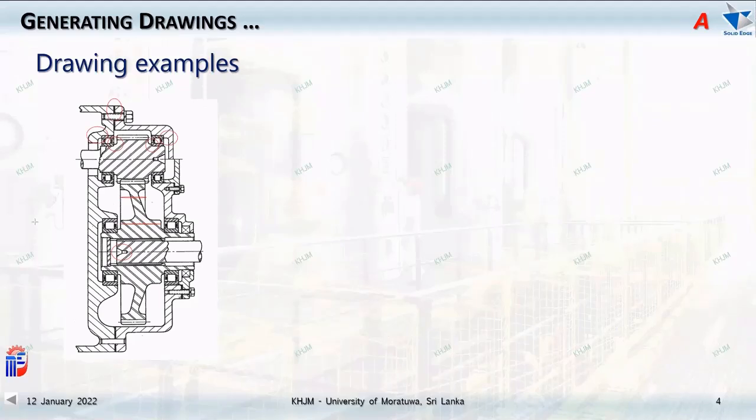Things you have to notice here: the shafts are stepped, and bearings and other things are already fixed onto the housing. All these things are required. And also maybe a small gasket or packing here, in order to accommodate the variations in dimension, as well as to have a positive sealing between the housing and this one.